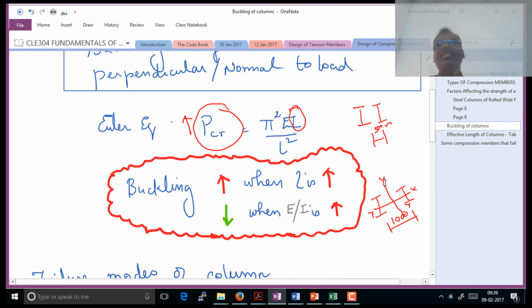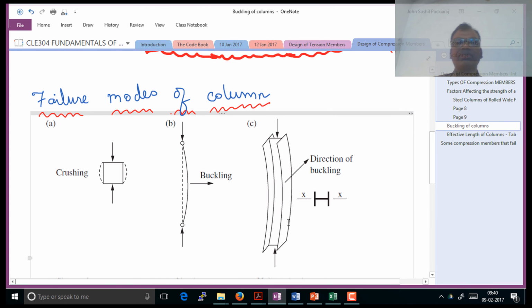Between these two, there's an increase of moment of inertia. Which moment of inertia increases, Ixx or Iyy? Iyy, you're right, because the distance from axis y has increased. So that is why Iyy increases. This is the way by which a designer can increase his I value. I'll come back to this principle a little later, but this is a learning which is very important.